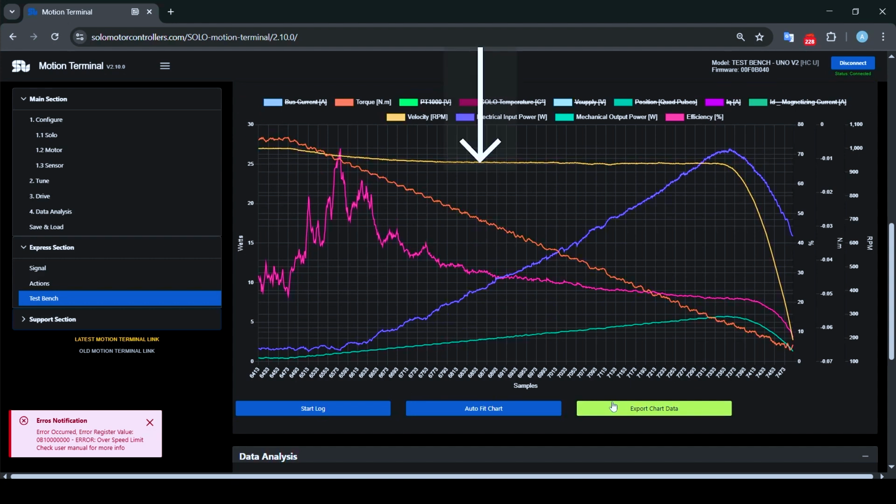In this plot, the yellow graph represents the speed of the system, which is at 1000 RPM, as observed. The orange graph shows the torque. This torque graph, influenced by the preset acceleration, is controlled up to a target torque of 0.1.